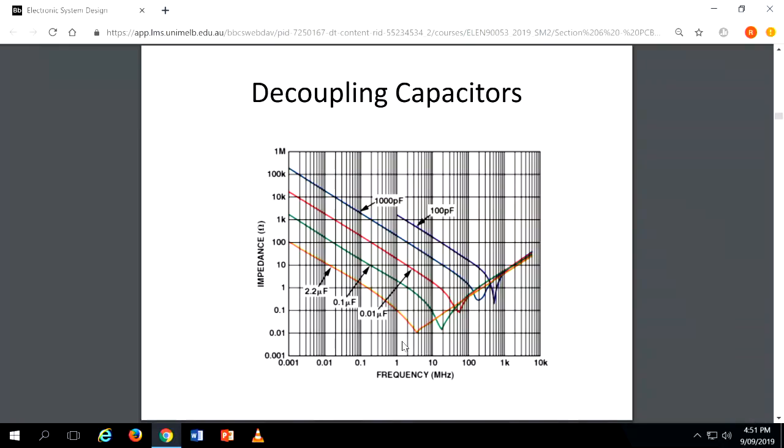It will happen with your copper track. When the signal frequency increases, the impedance of the track comes into the picture, which you did not connect. So that is the reason high frequency designs are difficult.